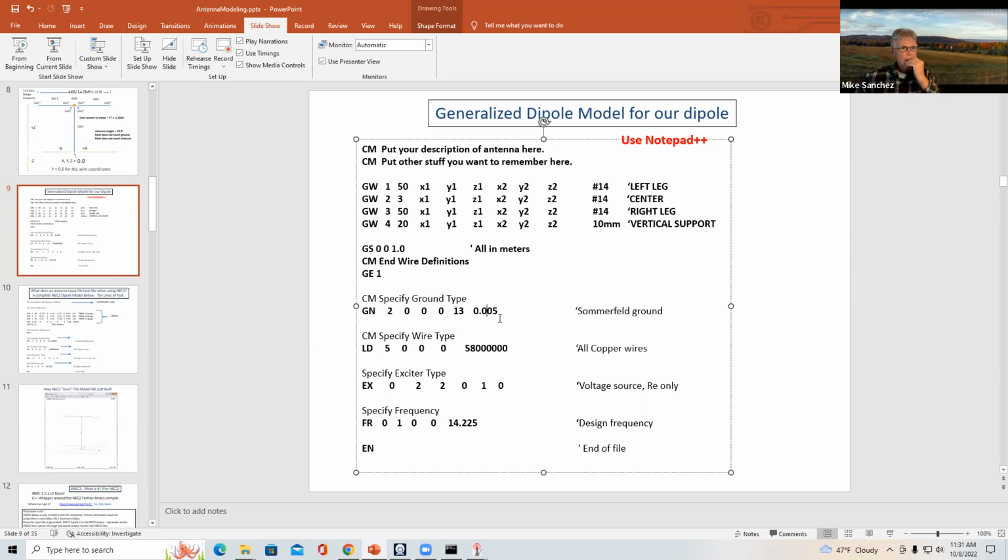Now, interestingly enough, I had another guy who has a dielectric constant meter measure it for snow, and it's totally different. So if you have snow and you want to see how the antenna behaves over snow, I can send you a different set of these numbers, and it'll change everything profoundly. So if you've ever gotten a lot of snow and you saw big differences in your antenna, that's one reason why.